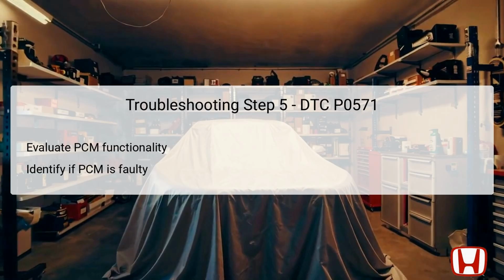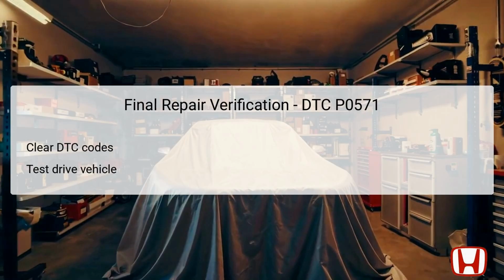It's critical that the PCM operates correctly, as it plays a vital role in managing signals from various systems, including braking and throttle control, ensuring safe vehicle operation. After completing the troubleshooting process for DTC P0571, it is essential to conduct a final verification of repairs. Begin by using the Honda Diagnostics System, HDS, to clear any stored diagnostic trouble codes from the vehicle's system. This step ensures that previous faults will not influence further diagnostics.